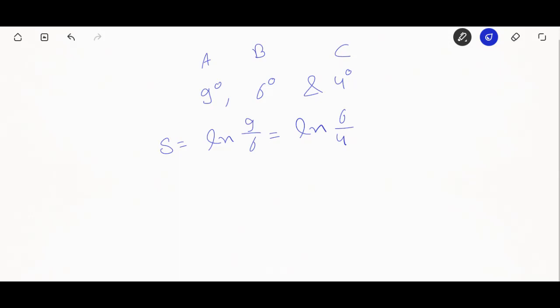4. Now if we need to calculate the cycles, if we have the initial and final amplitude, and we don't know how many cycles the system has gone through to get rid of that vibrational phenomena, we can use 1 by n ln x naught by xn, right?